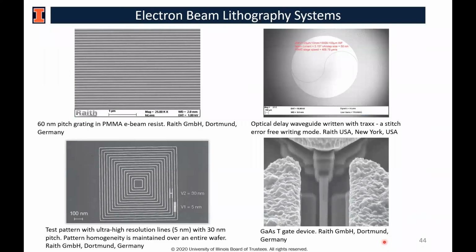Here are the SEM images of a performance test of the two Raith systems. The top two are the SEM images done by E-line. The left one is the image of a 16 nanometer pitch grating in PMMA resist. And the right one is the optical delay waveguide written with the stitching-error-free write mode.